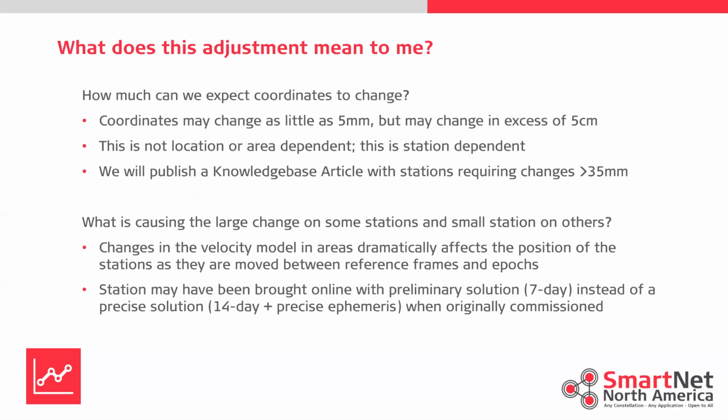But all you guys care about, after everything I've said, is how much can we expect coordinates to change? Well, coordinates may change as little as 5 millimeters. So you won't even see it in the noise. Monday morning, your recovery from the weekend will be more noise than that 5 millimeters. But it may change in excess of 5 centimeters in some areas. This is not location dependent or area dependent. This is station dependent. This could literally be from one station to the next station. So this is not an insignificant change if we are in and around or in excess of 5 centimeters.